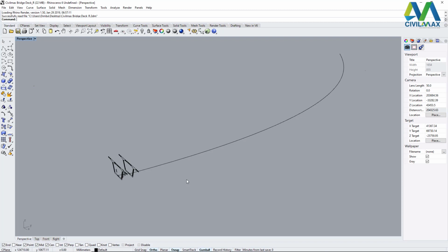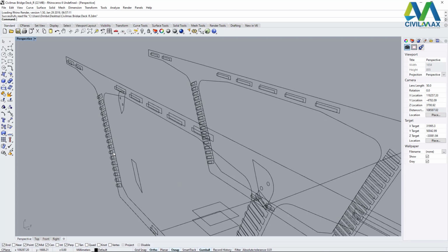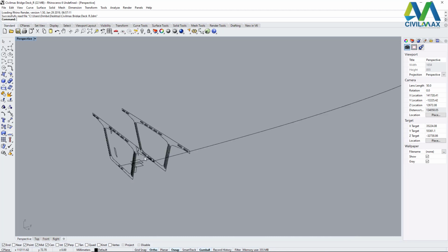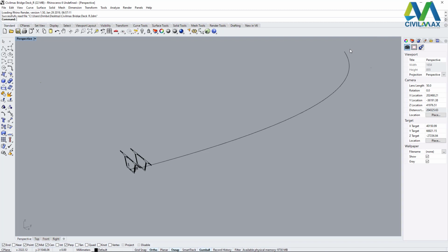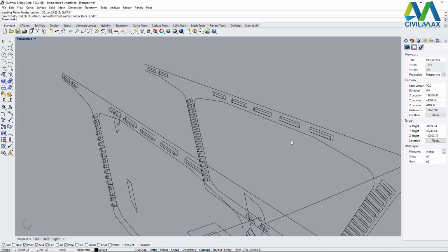In this case, if you don't have the coordinates in place and you have the exact dimensions of your deck as it is here, you can create your own deck and extrude to the specific dimensions, then array it along this path. That's the second option. The first option, if you have the coordinates, is that the coordinates will define the profile of the deck, so you don't need to do all this. Or maybe you can just do these grooves, and about these grooves I'll explain right away.